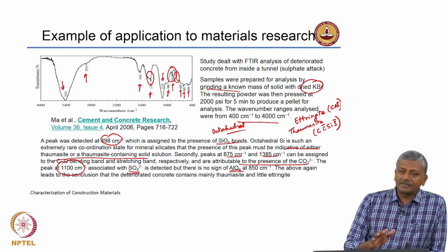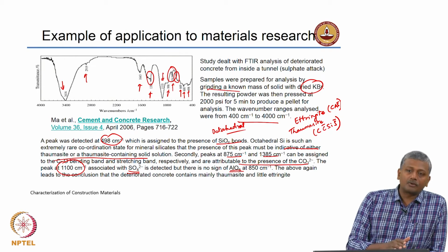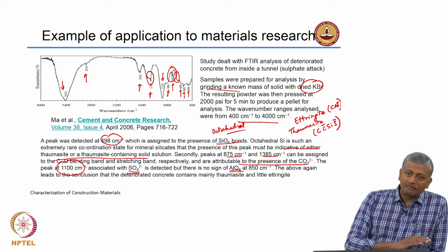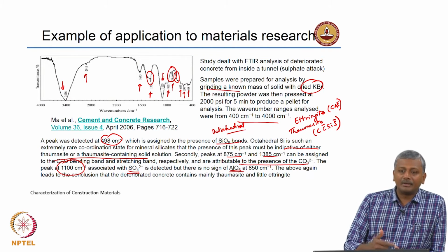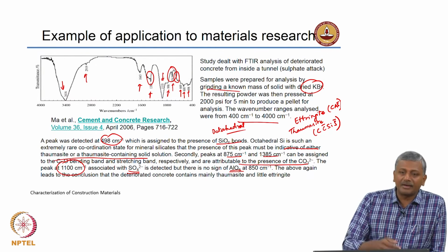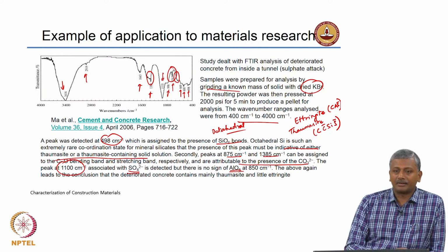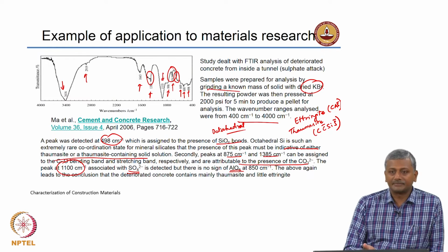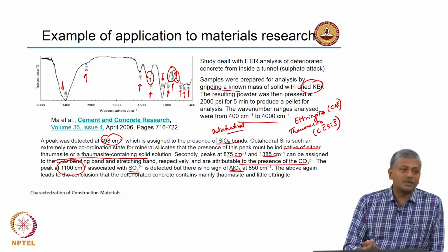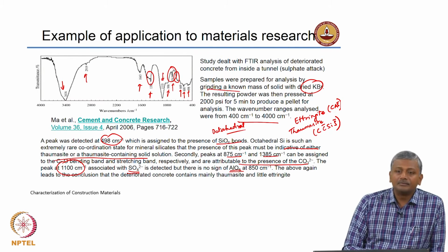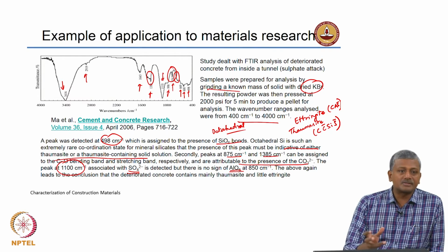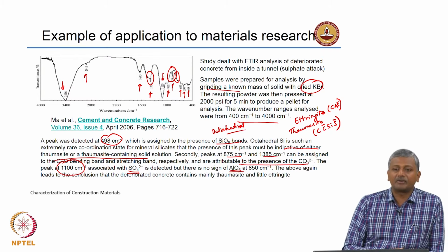And please remember, EDX is usually done with backscattered electron microscopy, where you have to polish the sample properly. So, the amount of work involved in backscattered SEM and EDX is far greater than what you do for FTIR. All you need to do is grind your sample. Preparation of the pellet takes a few minutes, you will see that when you actually visit the lab, and then doing the experiment takes you hardly a few minutes. So, all this information can be gained in a matter of minutes.